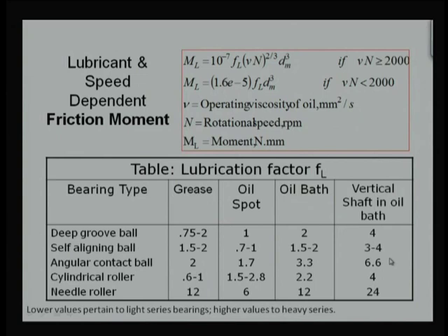And in this case, none of the single lubrication mechanisms is giving continuous lubrication of the rolling element bearing. Say with the oil spot, after some certain duration there will be oil sprayed on the bearing. In the oil bath case, oil is completely in a bath, so there will be some heat generation also, and it's very difficult to maintain an oil bath, particularly for a vertical shaft. That kind of bearing arrangement will not be very useful. So in that situation, we require a higher value of FL.